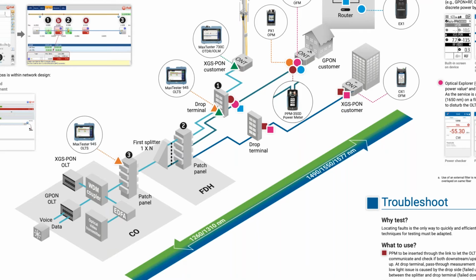So it looks like my first connection has got some high loss right here at the splitter, so I need to check that one. There's my, or actually, that's the connection to my unit. There's my launch cable. We do have a splice that has about a half a dB of loss, which at 1550 is a little more than that at this point. That sounds about right. Our second splice also was supposed to be about a half a dB. It looks like it's a little bit better.